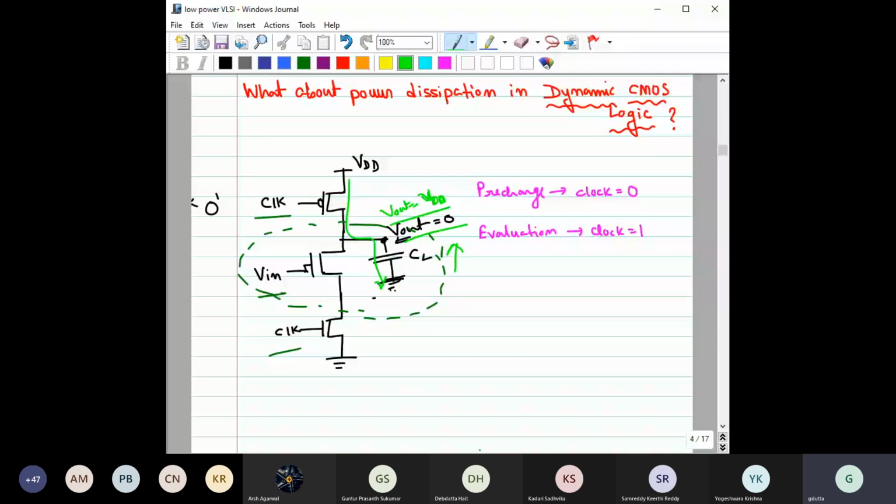So can we then say that the power consumption in dynamic CMOS is determined by the signal value probability of the output node, not by the transition probability or switching activity? So let us write this point. This is a bit important.